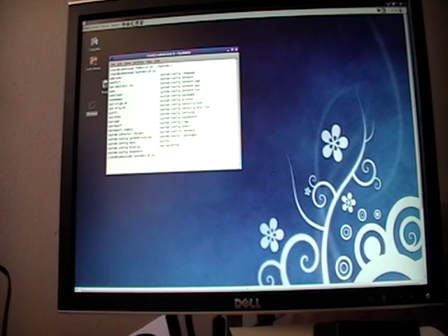if Verilog and VHDL are so powerful, why would you not want to use them? Okay, so I've been talking a little bit about gates. The reason why you would like to design in gates sometimes is that with Verilog or VHDL, you do not have control of speed, area. You can't optimize them, speed, area, or power. Those are important things when you're designing a circuit.